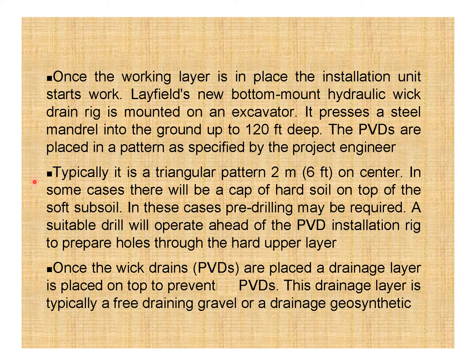In some cases, there will be a cap of hard soil on top of the soft subsoil. In these cases, pre-drilling may be required. A suitable drill will operate ahead of the PVD installation rig to prepare holes through the hard upper layer.